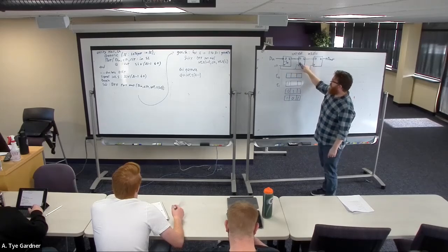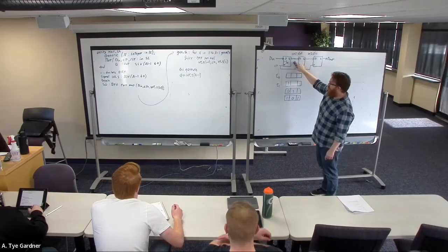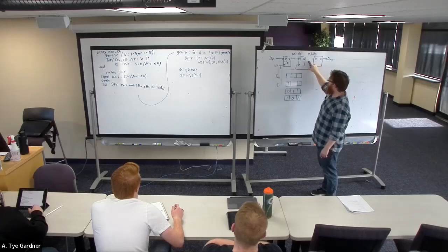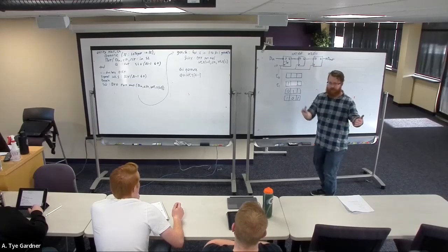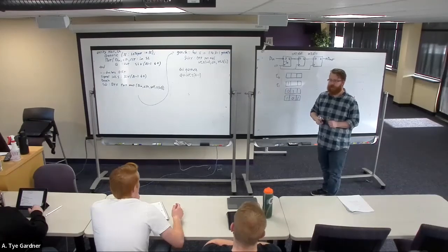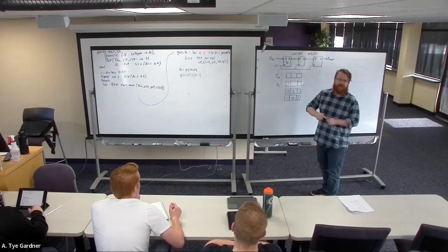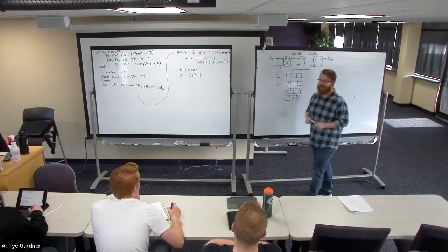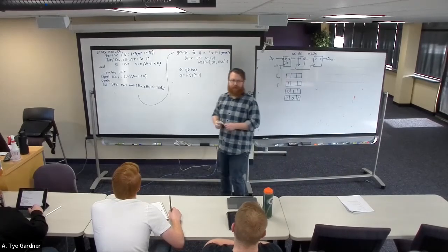The first generate will take int S at 1 and connect it to the output, int S0 is the input, and it will just build a whole chain for me of n length. Anyways, it turns out you can build full adders the same way. You can build an n-bit full adder.